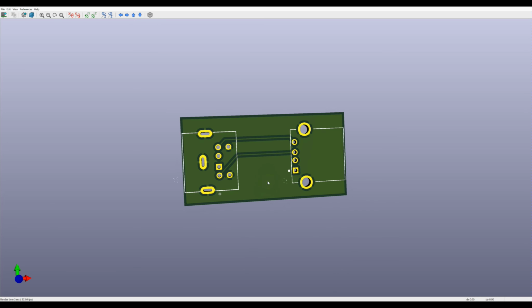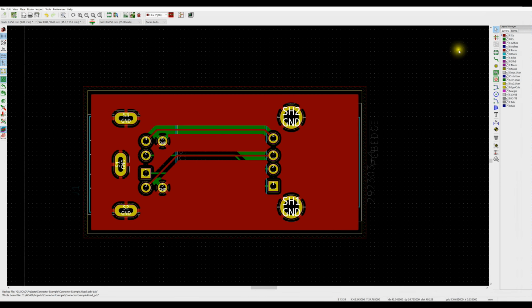It's a really simple board. But you know, it's a good start. It got me the connectors I wanted. Everything looks like it's probably reasonable pinout-wise. So really nice. So hopefully this little tutorial, from digging around in KiCad to actually getting footprints and device symbols in the library, makes sense. You can see here that the connector actually sticks out a bit from the board, and that's exactly what I expected, the shell of the connector slightly off the edge of the board. Those connectors have got me what I wanted, so I'm happy with this. So I guess with that, we'll wrap this quickie video up, and we'll talk soon.